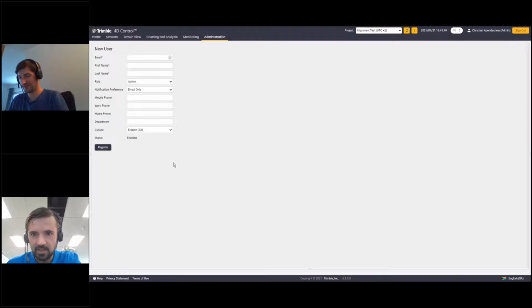Another question was asked by Ruli: can the alarm definitions you're showing in T40 be set up to sound an audible alarm or a siren? Yes, you can also run a batch file. If an alarm is triggered, you can run a batch file, and the batch file in turn can trigger a siren, for example. That's possible, and we also have some installations doing that.